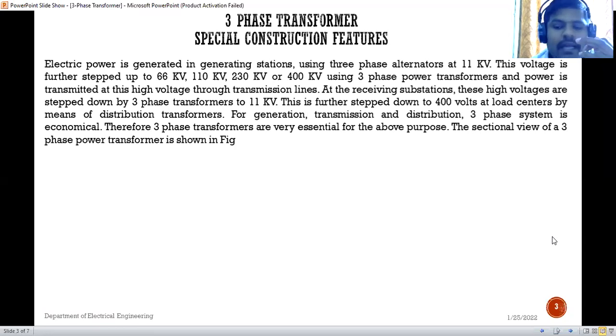Now there are some receiving stations, or receiving distribution substations required, because the consumer requirement of electricity is at lower voltage. Some industry requires a voltage of 33 kV, some industry requires a voltage of 66 kV. Some domestic consumers, like our home appliances, run on 230 volt, and our agriculture field appliances run on 440 volt.